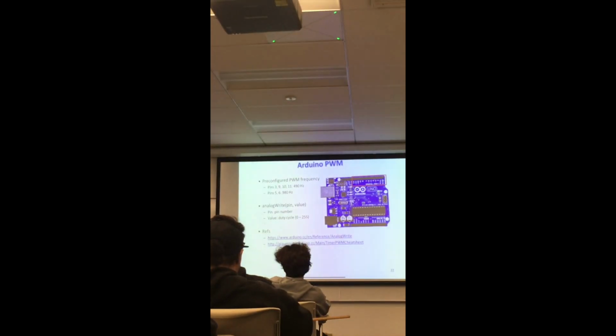Okay, so it assumes that you either take care of it or you don't care about the actual value. By taking care of it, I mean that you follow it with a low-pass filter, if you really want to obtain a DC value of some sort. Or you are connecting that output to some sort of driver, which will take care of it. So it is good to understand that there's no digital to analog converter within Atmel microcontrollers.